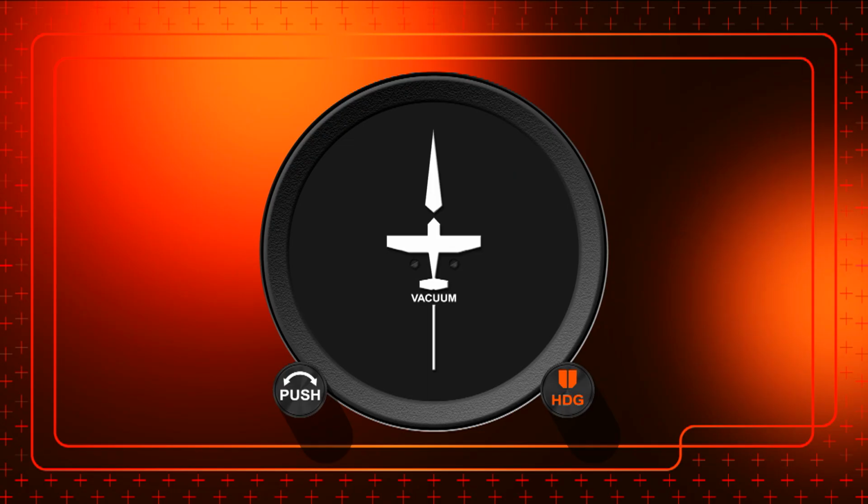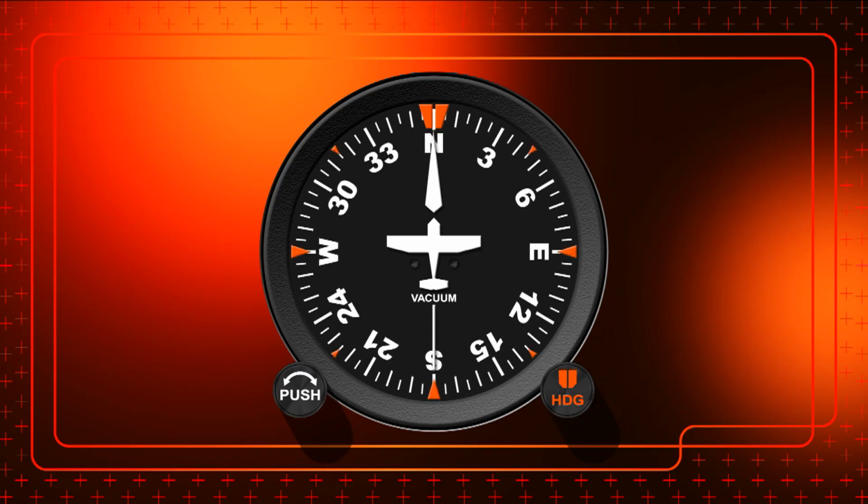Finally, the instrument also incorporates a miniature aircraft symbol. This provides the pilot with a visual representation of where the aircraft is heading, when the point of the miniature aircraft symbol points to one of the heading degrees on the compass rose. As you can see in this example, the point of the aircraft symbol is pointing to the letter N, which means the aircraft is heading 360 degrees.